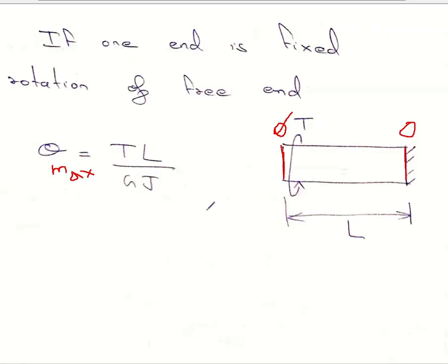When you substitute based on this equation, you can be asked a question, that the maximum value of rotation of a cross section is to be limited to 2 degrees or 3 degrees. Then you will have to convert that 3-degree value into radians, then substitute in the equation to find the maximum twisting moment that can be applied.